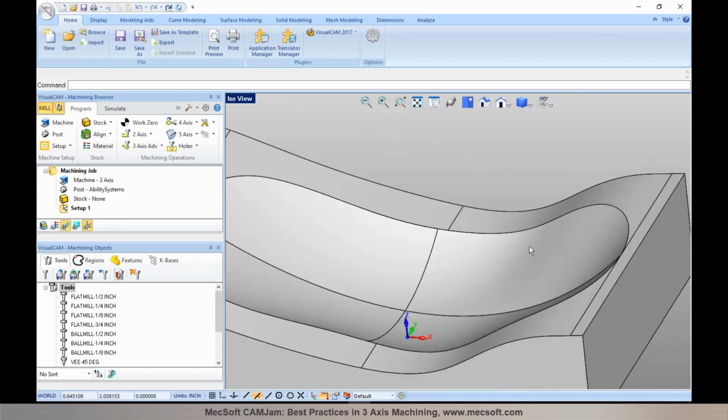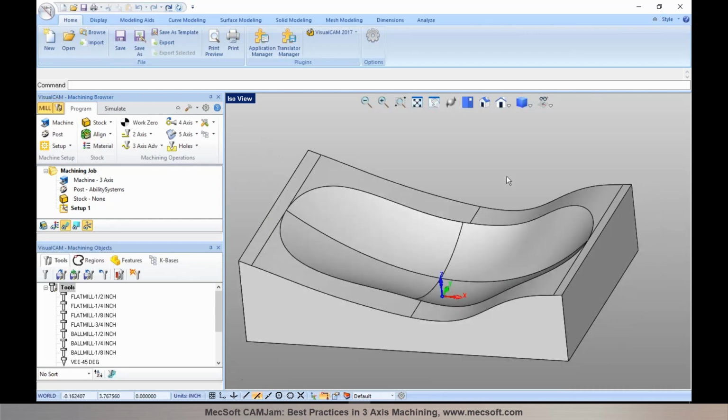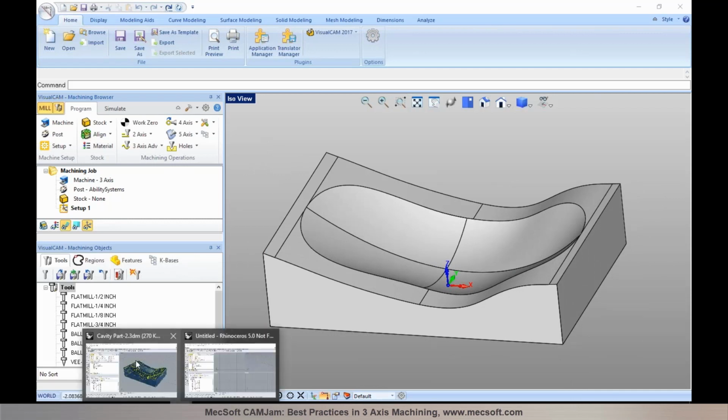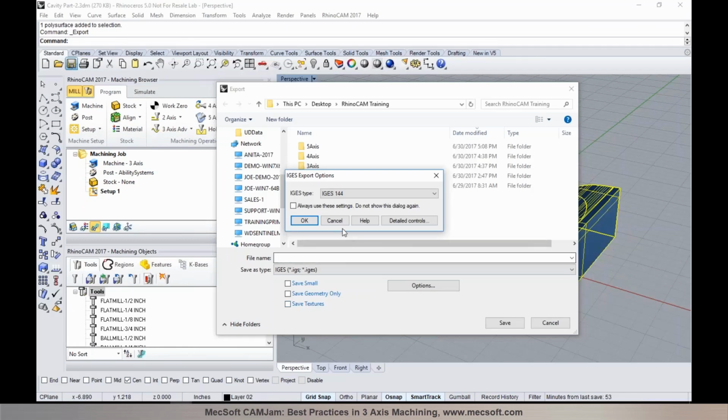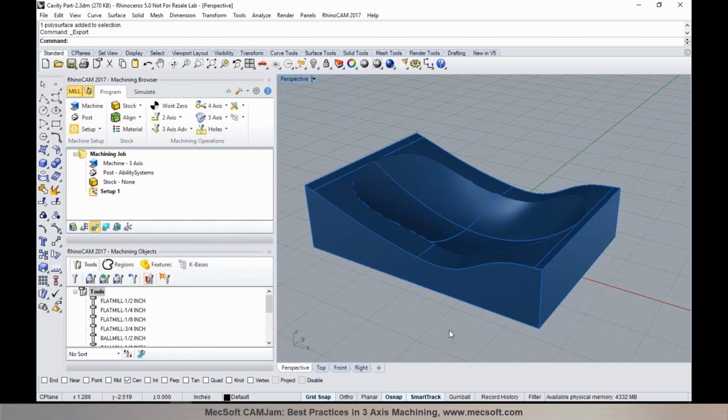So the first step when you're working in Visual CAD/CAM is, as you load the part, to check your part faceting tolerance, to see if you imported it at a good tolerance, tight enough for the accuracy and the surface finish that you're looking to accomplish on the part you're looking to machine. Now, in Rhino and SolidWorks, we actually use the machining tolerance to determine the surface finish of the part.